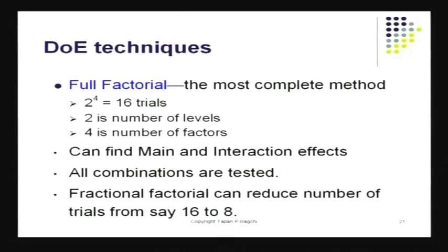But if these experiments become too many, I have to use some other method, which is called running a fractional factorial run. And that I'll show you once we get into that. I'll show you how we come back from full factorial design to a partial factorial design. And that's actually a pretty efficient way to find a lot of information without having to run all the different 2 to the power k experiments, which is like the full factorial design.